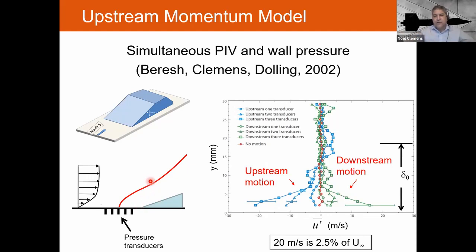And then he would average all those, and he would get profiles, but also the velocity fluctuation. Now, if there's no correlation between what happens upstream and the shock foot, then your u prime should average to 0, right? u prime bar is 0 in a turbulent flow, but not if there's a systematic correlation.